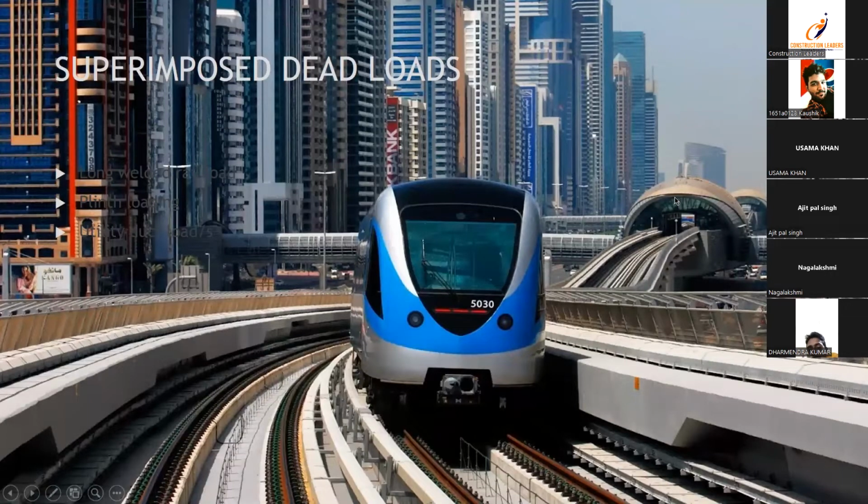This is a typical picture of one of the Dubai Metro. These are the stations. If you see on the track, it is not only a plain deck. Over here we have got rails, plinths, and some utilities. Over here we have some railings. If at all we've got some street light over here, then it has to be represented as load. Then if you've got conduits like this running, you have to have all of them included in the SIDL load case.